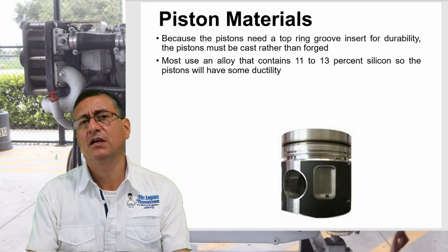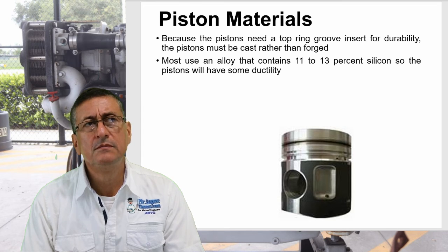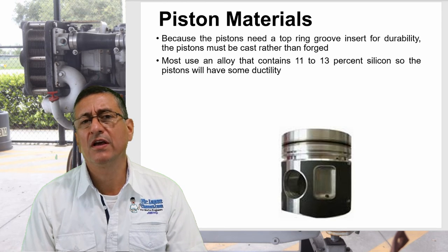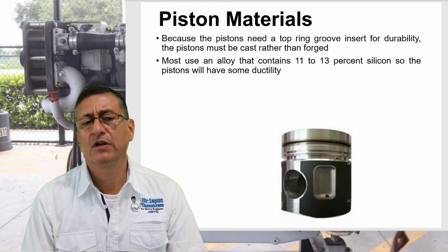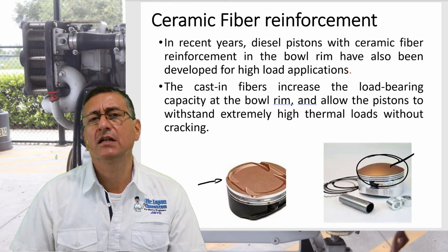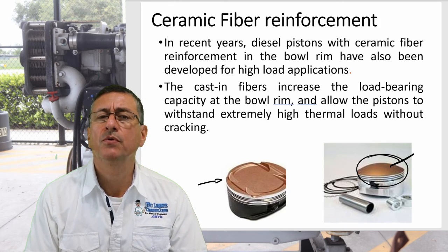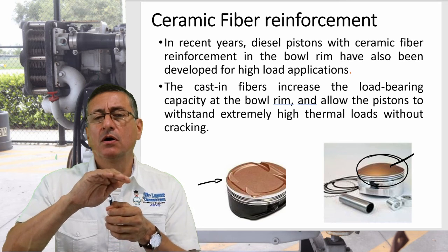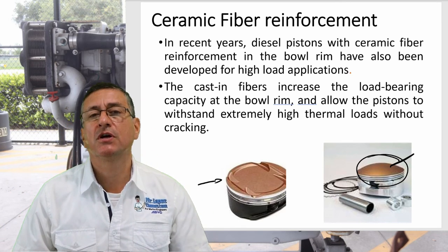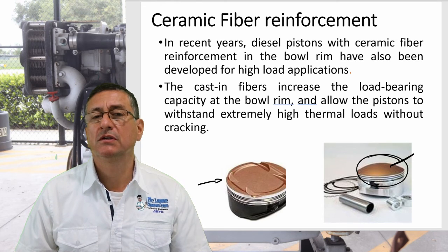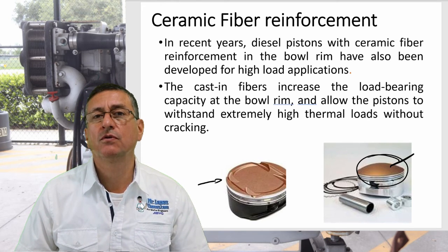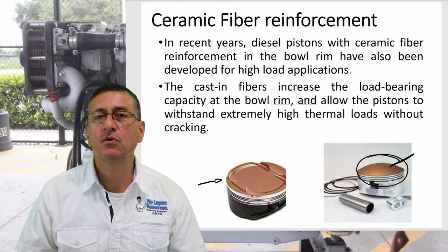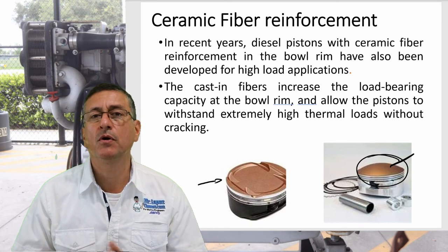Other important consideration is in relation with some tricks used by engineers in order to improve the efficiency of the pistons. For example, when people use ceramic materials on the head of the pistons in order to improve the heat transfer, and in order to reduce the volume of the combustion chamber to increase the compression ratio. This is a very common technique used by engineers dedicated to convert regular engines into high performance engines or race engines for race car, race boat.